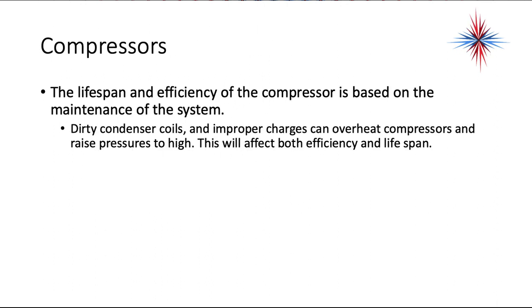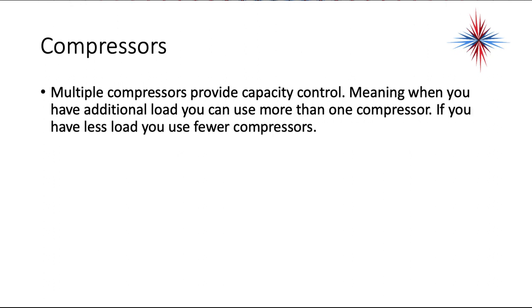The lifespan and the efficiency of the compressor is based on the maintenance of a system. Dirty condenser coils and improper charges can overheat compressors and raise pressures too high. This will affect both efficiency and lifespan.